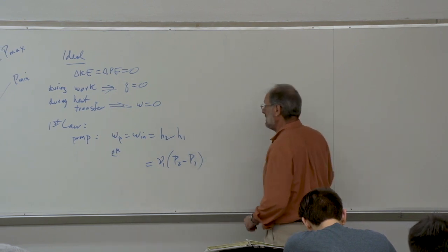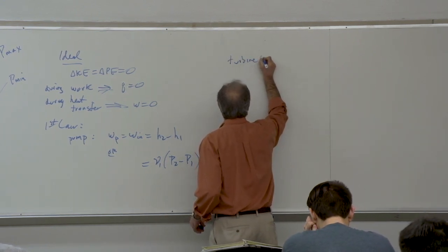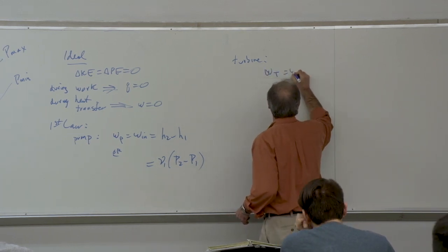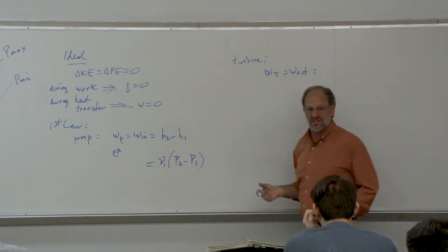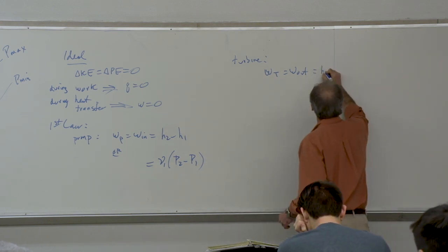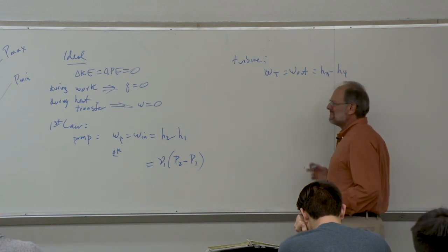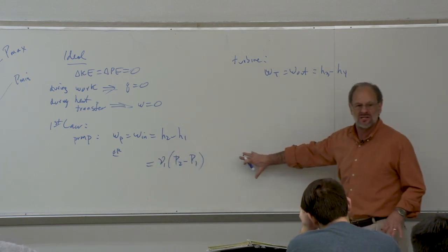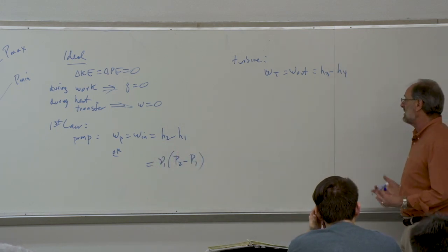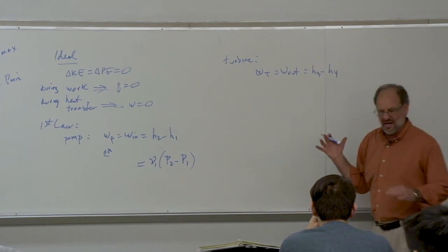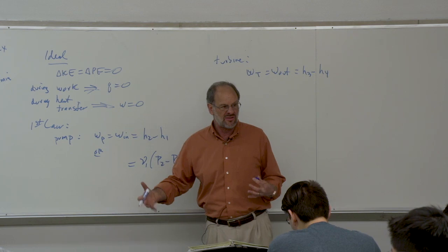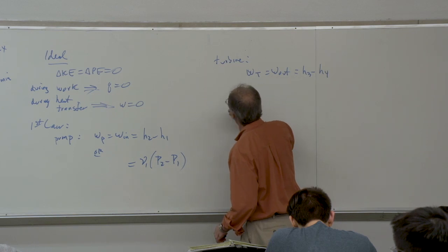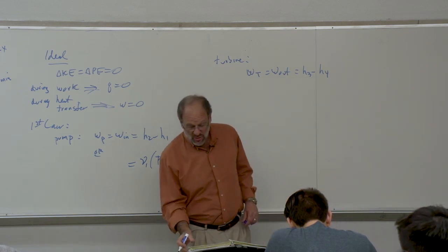When we deal with the turbine, again, the turbine work is our work output. And again, this is just the enthalpy change as we go from 3 to 4, so just H3 minus H4. Keep in mind, again, all these terms are absolute values, right? We know the pump work, the magnitude is positive, but it is work input. Technically, it's negative work, but we'll just let those work terms have their sign included within the various equations, like the thermal efficiency equation. Again, a reminder of what we already know. So here's our turbine work equation, and there's really nothing more we can add to this.